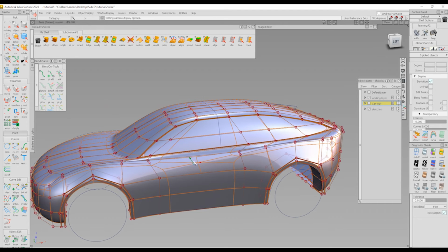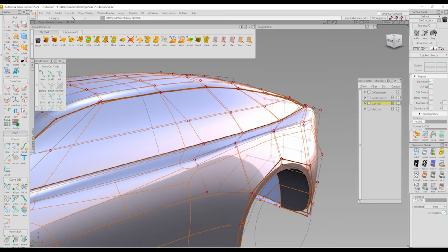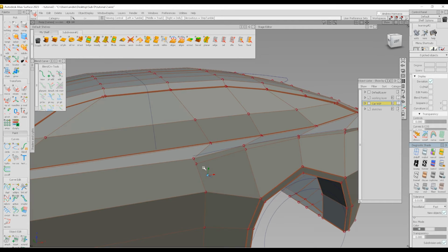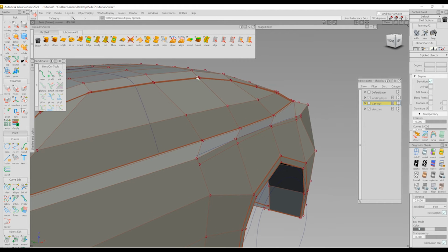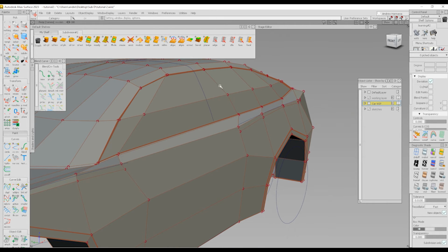And now I think is a good time for me to explain that in SubD, most faces, these hulls and CV rows, create a four-sided surface or a four-sided face. And that's how SubD works. It works better when each of these faces is created by four sides or four CVs. So if you look at this one, it is created by 1, 2, 3, 4, 5, 6.